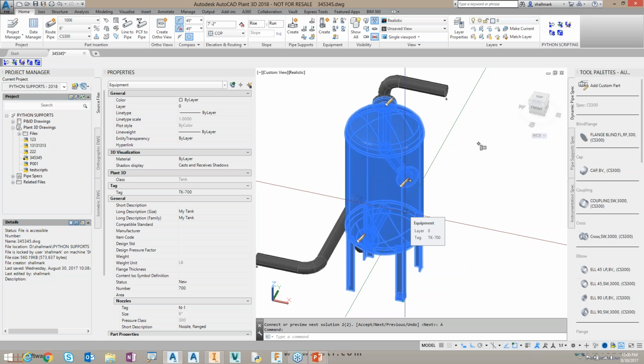I know with an ADSK, prior to creating it, we can simplify or shrink wrap that tank. So if there's a lot of stuff going on inside that tank, I certainly don't want that kind of detail in Plant. I can simplify that and create an ADSK of it to get the file size down. But yeah, there may not be a benefit other than that. There may not be a benefit to using the ADSK over the IAM.